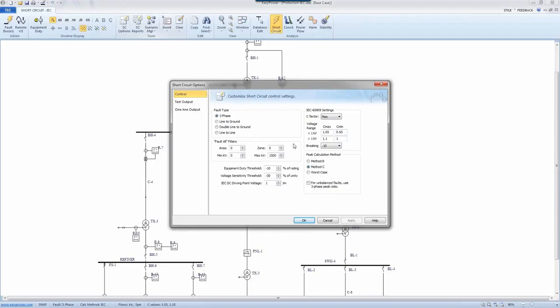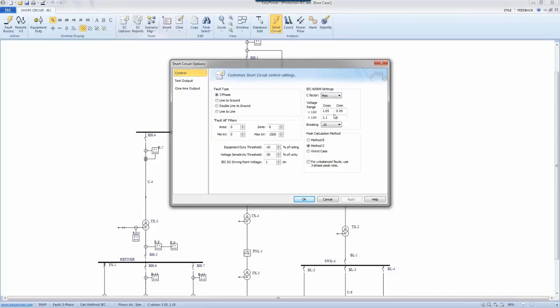If any K factor has a C value in it, once the C value changes, those K factors change, and they are going to impact, let's say, the transformer impedances, and some other K values that we define and use in, let's say, method B and method C, and all those details. Those are already implemented. Another factor is that when we use Cmin, we cut off all the motor contributions. That's one step we take to minimize the short circuit current, and I'll get to that and show that one too.